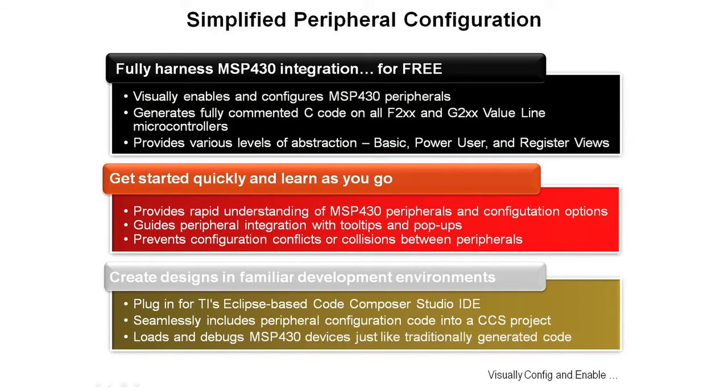The intent of Grace is to simplify the peripheral configuration, to allow you to fully harness the MSP430 integration for free, to visually enable and configure the MSP430 peripherals. It will generate fully commented C code on all F2XX and G2XX value line microcontrollers. Fully commented, human readable code, not some kind of strange stuff that you can't understand what's going on.